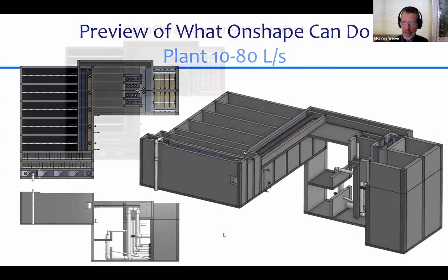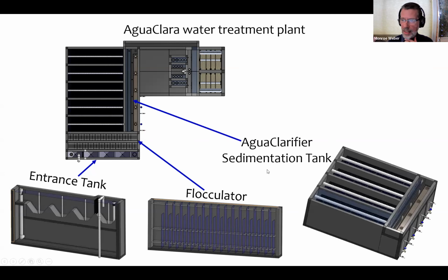In the flocculator, the water has to go up and down, up and down, and go through many expansions and contractions and generate lots of turbulence and ultimately generate lots of collisions between particles. From there, it passes into the sedimentation tank.